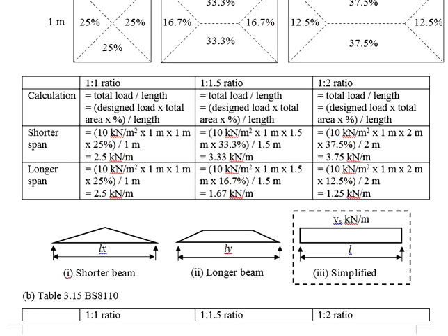However, for simplicity, we will assume that the loads are equally distributed throughout the span. That means we will assume the total loads of the triangle being divided by the total span, giving us a uniformly distributed load. Same principles apply to this trapezoid load. Total loads divided by the total span, you get the uniformly distributed load.